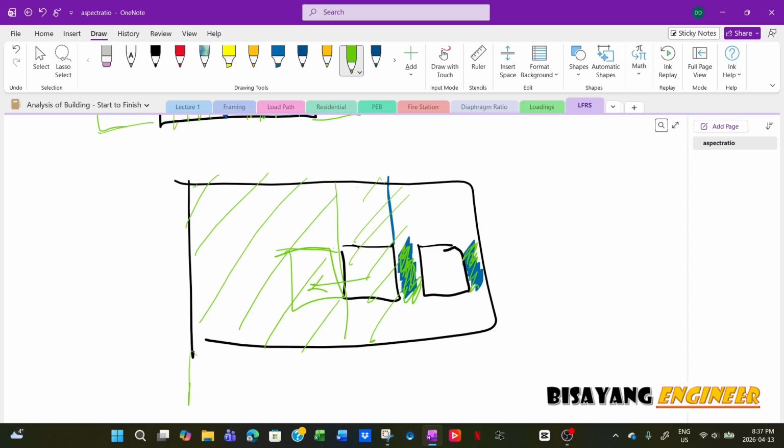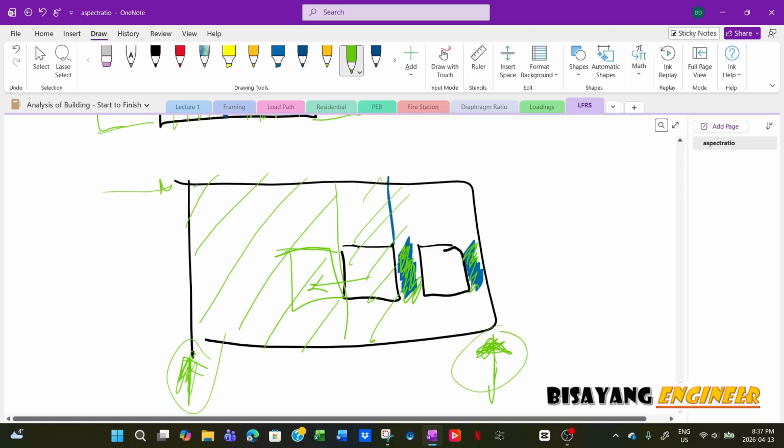Then that's better because you now have a full length of your shear wall panel, and then you can reduce the uplift. When you check for overturning, because the forces are spread really far apart, you will have smaller forces right here. And then you are utilizing the entire wall with the force transfer around opening.